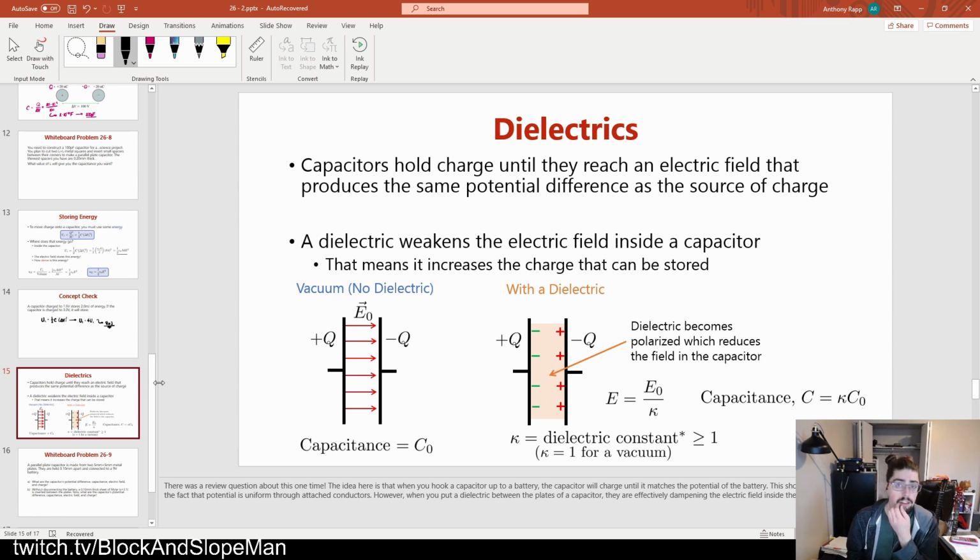That's not actually a bad thing, though, and it's a very useful thing. Because all of these things that I'm seeing here, so we just talked about a problem where we had 100 picofarads, and to get 100 picofarads, I had a 4.75 by 4.75 centimeter square. Think about that size for a minute, right? That's like the palm of your hand kind of size.